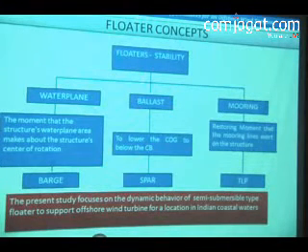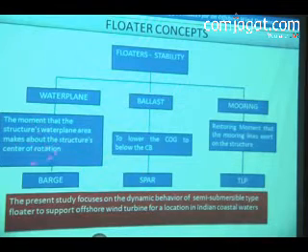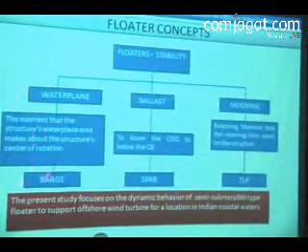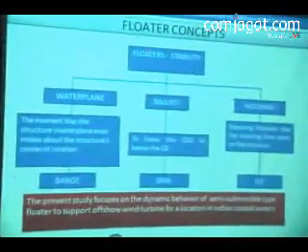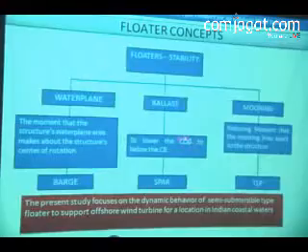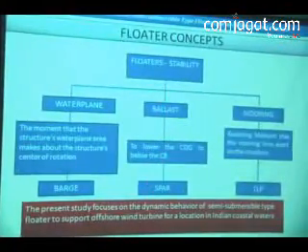When we think of floaters, how are they going to give stability to such a massive structure? One way is through the water plane area, the moment the water plane area makes about the structure's center of rotation. An example is a barge. Then there is the ballast-stabilized floater, with the center of gravity lower than the center of buoyancy. That's the spar platform concept.